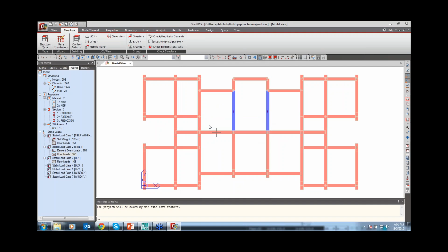If two walls from the geometry get the same wall ID, it averages the stresses, so you might get the wrong answer. So different wall IDs are important. If you are using ETABS or other software, you know that the pier label, or this type of wall ID, is very important for designing. For the analysis it is okay, but for the designing it's very important, because for the particular wall ID we are giving, that much length is considered for the design.